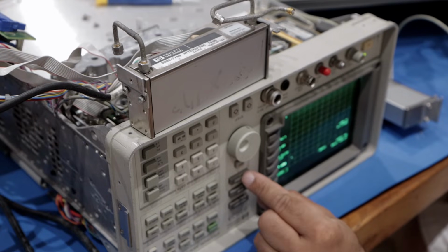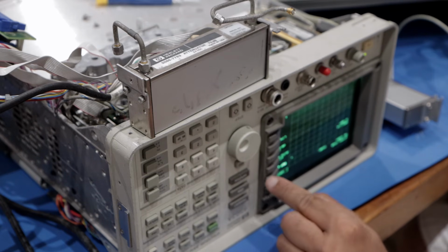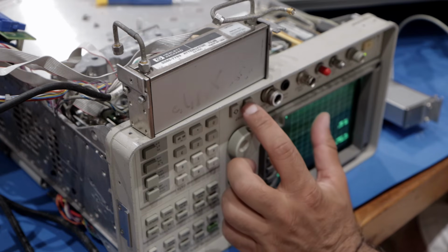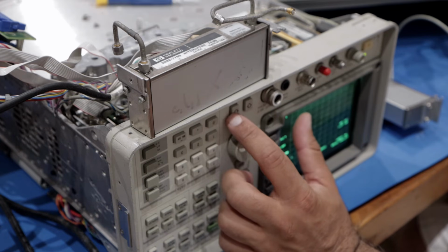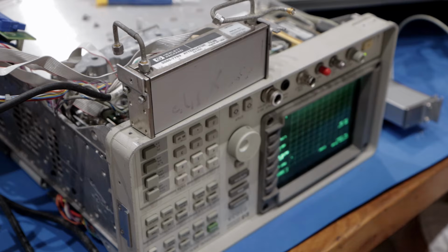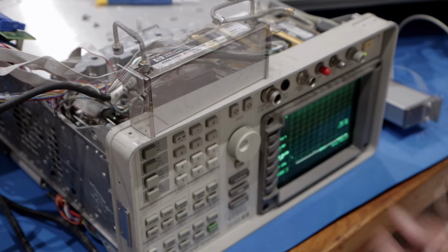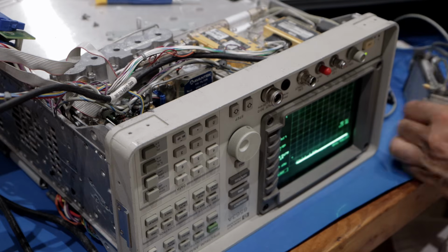So, I've ordered the used oscillator. While I wait for it to arrive, I'll tackle another issue. Here's something odd. From the moment this analyzer first booted up until now, I haven't heard the attenuator click even once. So I'm controlling the attenuator manually through the menu. Still no clicks. Here's my plan. I swap it with the attenuator from my 8560A as they are pin-to-pin compatible.